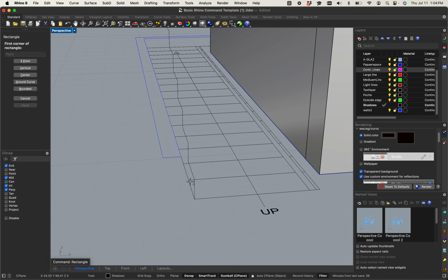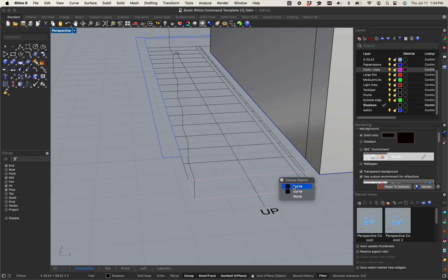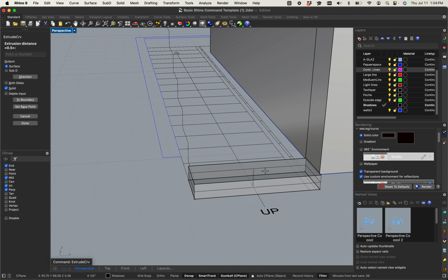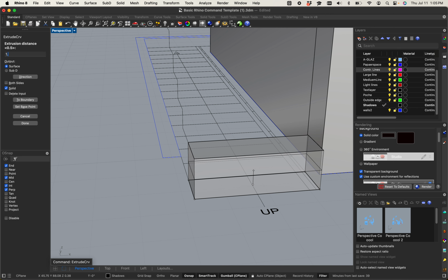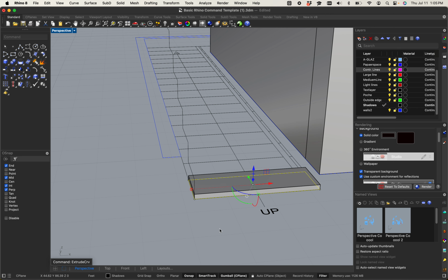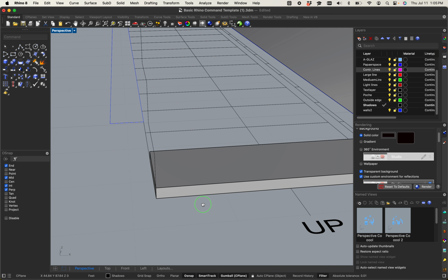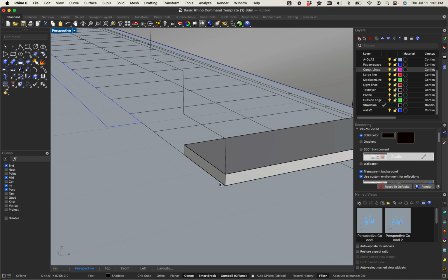So I'm going to go ahead and hit rectangle. And I'm going to redraw that because, well, I want a perfectly closed one, and I already chopped up the rectangles with my rails, so that would be kind of silly. Extrude. Let's go with about 1.5 inches thick. It's looking like a pretty sweet stair. Now don't get me wrong, I could do even some more detail to this, and I would do it to that one stair, especially if I'm going to copy it over and over again.